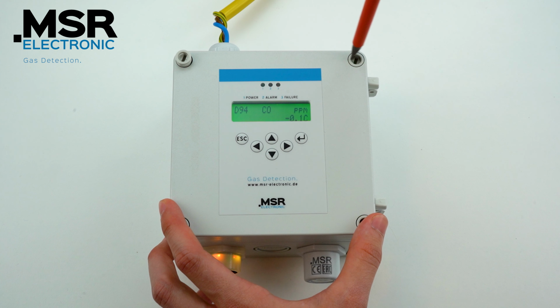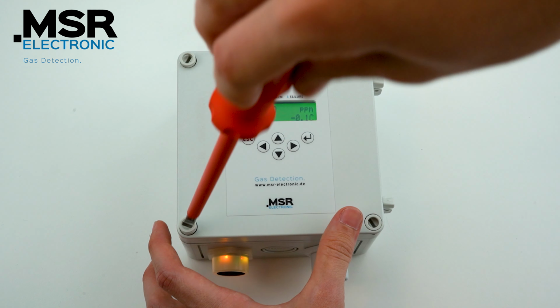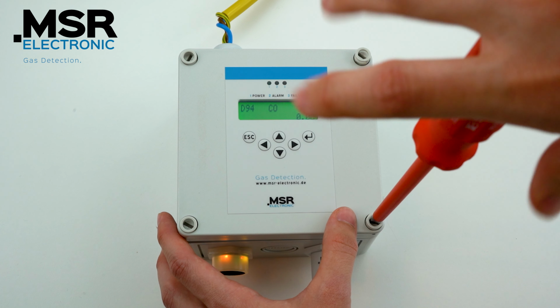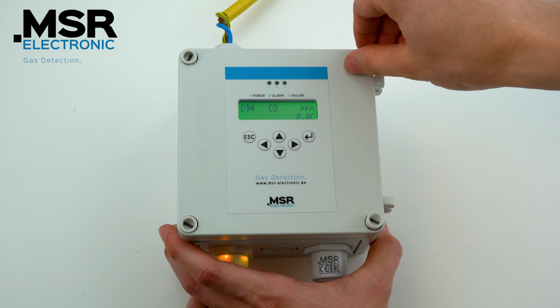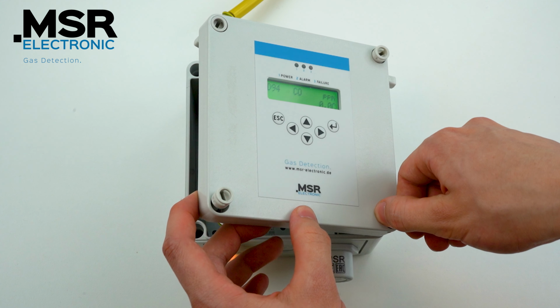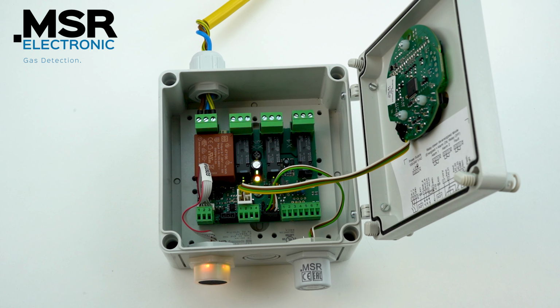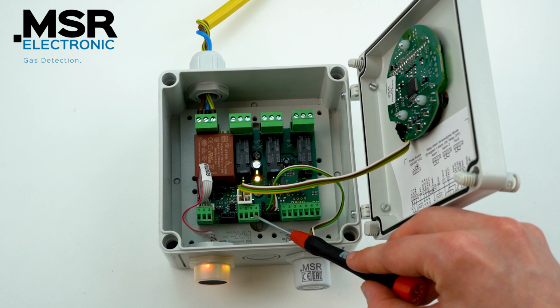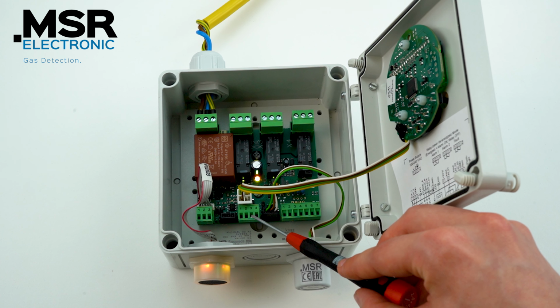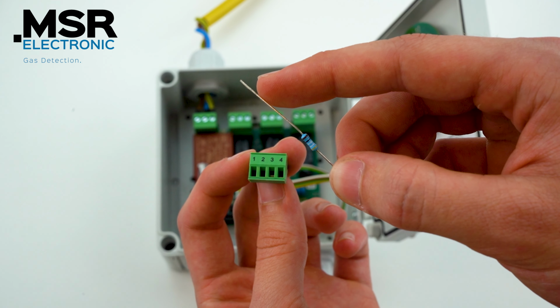To fix the error on the hardware side, first loosen the 4 housing screws and then carefully lift off the cover. Depending on the application, we now install a resistor of approximately 500 ohms between the analog output, terminal X12 3, and ground, terminal X12 4.